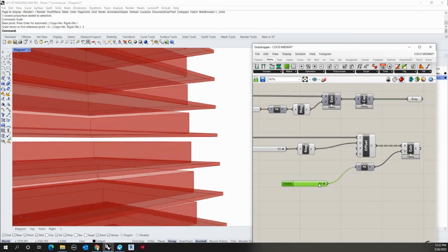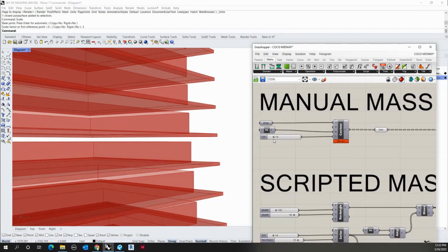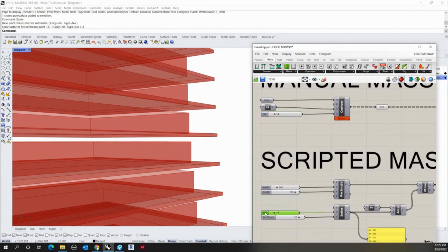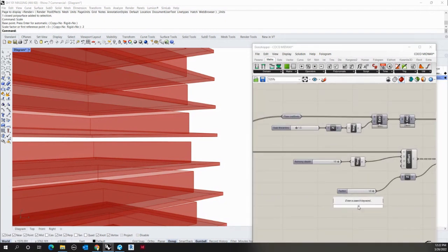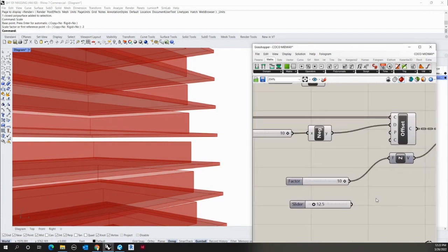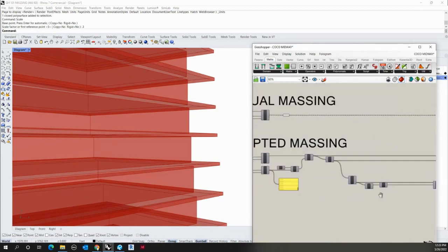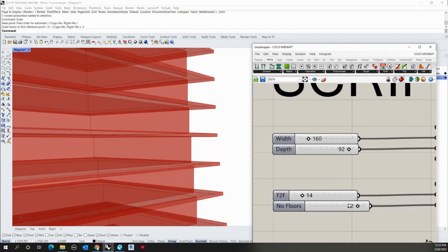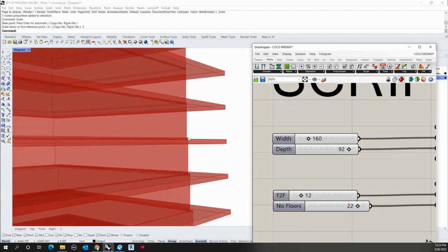Then it doesn't quite work. So you would change it to, in that case, I believe it was 14 feet. Yeah, 14 feet floor to floor. And my slab being 1.5, I need 12.5. But this seems like a slightly awkward process, because now that this is correct, if I go back and decide to change my floor to floor, it's maybe going to be 12, and suddenly my facade elements are too tall.